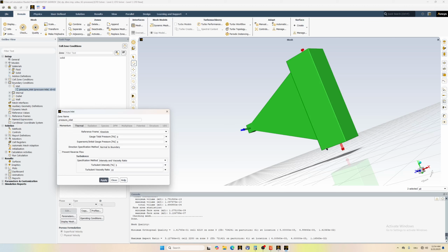So you reach huge densities even with modest inlet pressures. You can try with, let's say, 200,000 pascals, which is about 2 bar, and initial pressure here just slightly less than the total pressure. It doesn't really matter this value. It's just to start the flow in the simulation.